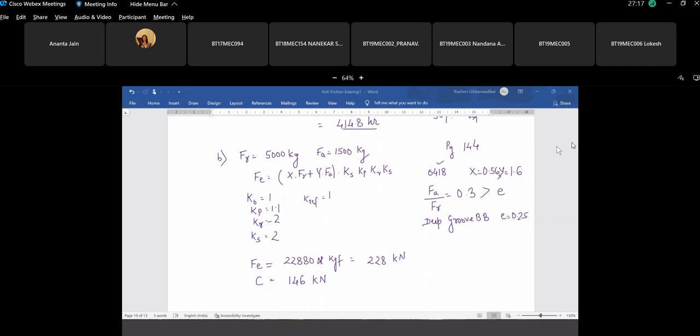When the bearings are rotating in opposite direction, it is not affecting the RPM, but it is affecting the kind of loading. As I told you, these values that are given in the design data book, the dynamic load carrying capacity, the value of C, are for certain conditions. In a lab condition, it is assumed that the inner race is rotating and the outer race is fixed. As the conditions change, the bearing is subjected to heavier loads.